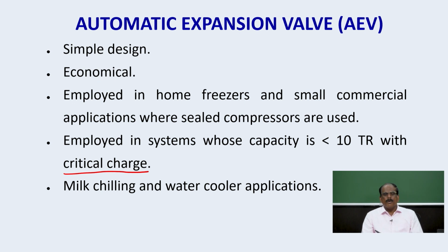One piece of information I would like to add, which I forgot when we were discussing the capillary tube: in a capillary tube, two types of pressure drop take place. One is the frictional pressure drop, that is the pressure drop due to friction, as the fluid has to overcome the resistance offered by the walls of the tube. The second is the momentum pressure drop, which is due to the acceleration of the liquid as some of the liquid is flashed into vapor. So, those are the two types of pressure drops.